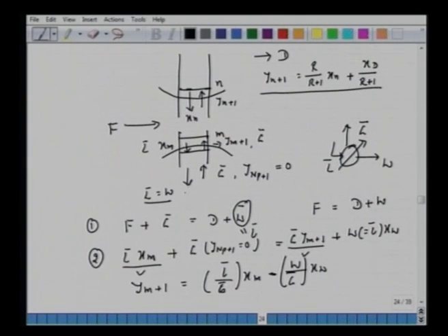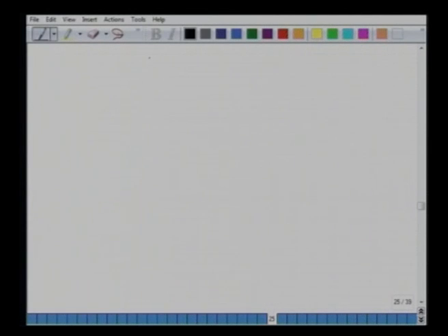Here we are saying that there is no reboiler, so this product L bar is nothing but the product W. So these are new equations where L bar equals W. We see one modification in the overall balance, and the difference equations have the same format except that L bar is the same as W. So let's see how we can plot this on the McCabe-Thiele diagram.